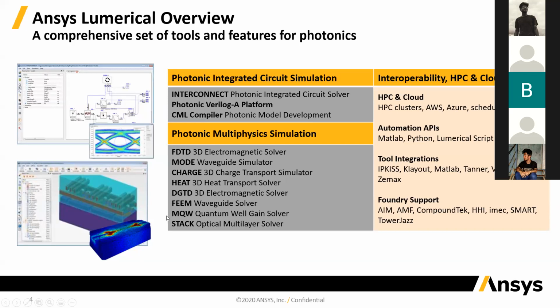We have a relatively new solver called MQW, which is a multi-quantum well gain solver. And this can be used to simulate, for example, the gain spectrum of a multi-layered stack. These are very typical and very useful in, for example, III-V based lasers or electroabsorption modulators. And then finally, in this category, we have STACK, which allows you to easily simulate multi-layered optical devices. So these are the multiphysics simulation tools that allow you to simulate individual components.